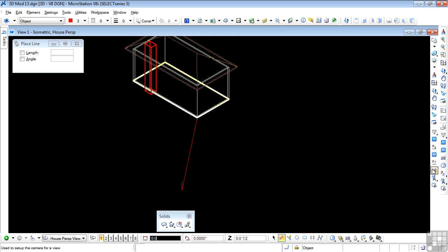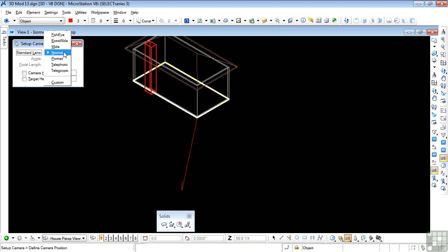So we'll start the camera tool. The first prompt is to select the active view. Well, that's this view, data point in the view. Now we can select a camera lens. So I select the wide camera lens. Because I've done that, these 2 boxes are grayed out. I don't care about these 2 because I have my camera set where I want it. And we follow the prompts.